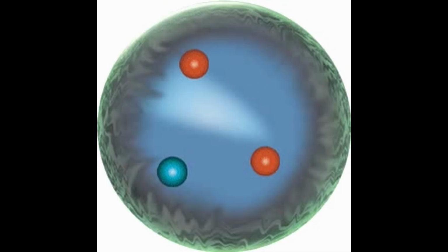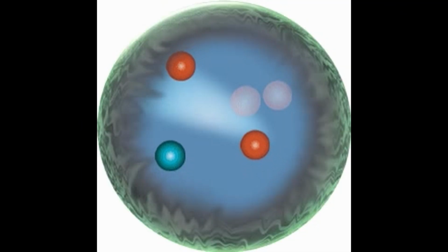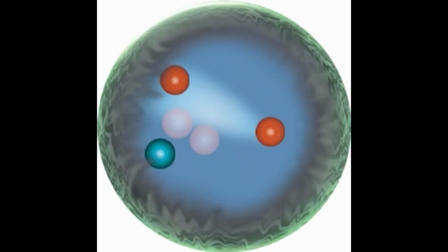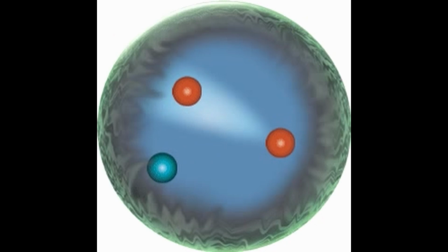5. Single electron transistors, SETs. Quantum dots exhibiting the Coulomb blockade effect are used in single electron transistors, SETs. In SETs, the ability to control the flow of individual electrons through the quantum dot allows for extremely sensitive charge detection and manipulation, making them useful in various applications, including quantum computing and nanoscale electronics.